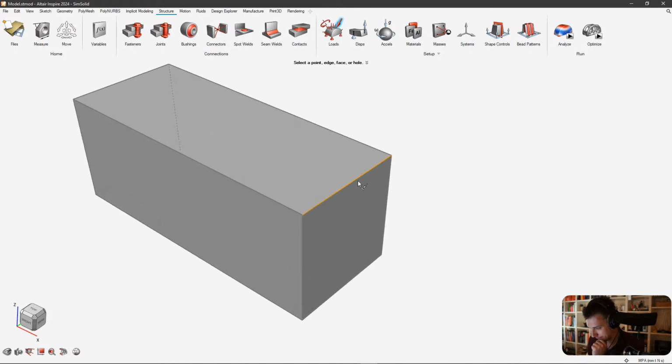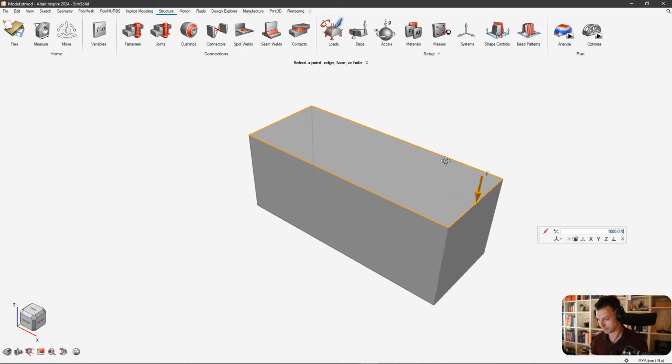All right, then maybe put a little force here, kilonewton maybe, and put it. That's also a cool trick, right? You can just double click on here to change direction. You don't have to put a minus here and press enter like I did before.